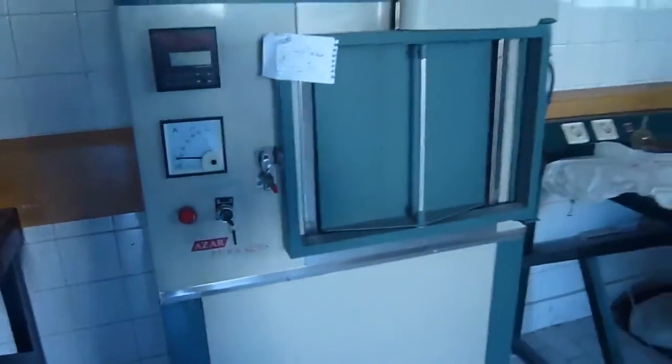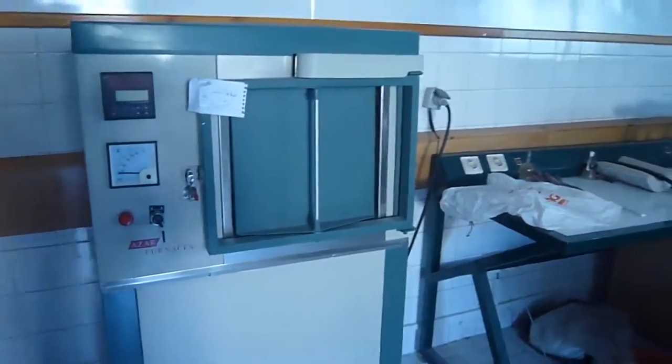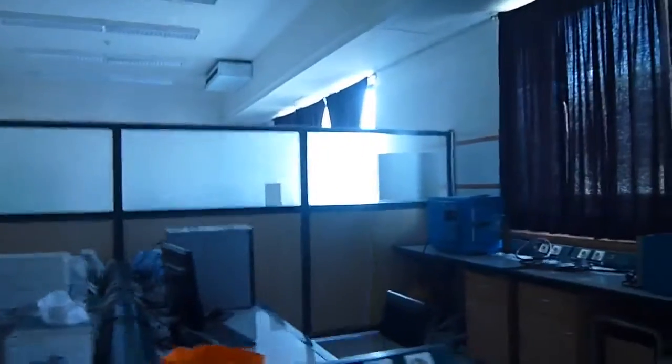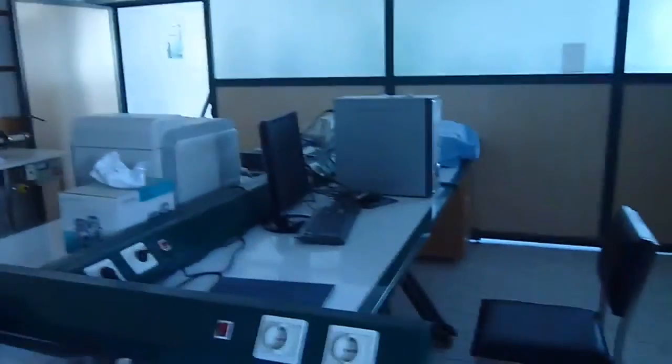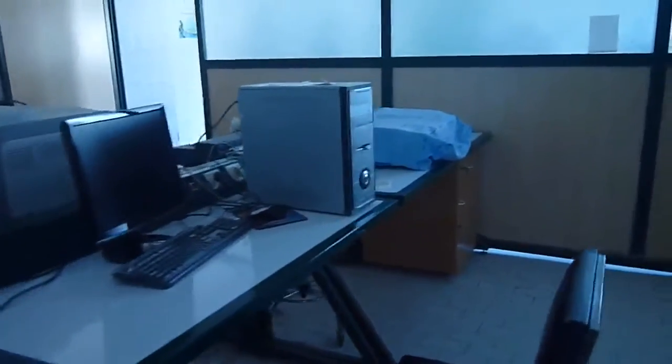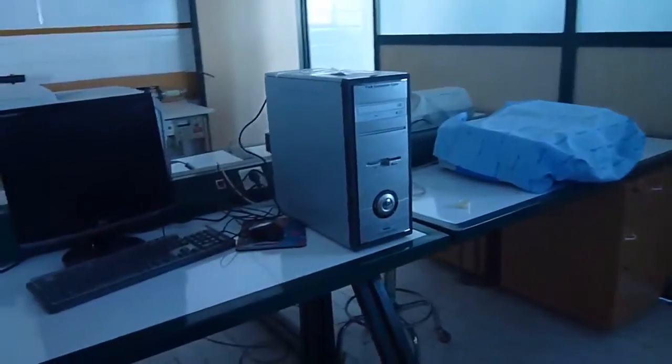Copper, silver, and brass can be cooled slowly in air or quickly by quenching in water, unlike ferrous metals such as steel, which must be cooled slowly to anneal. In this fashion, the metal is softened and prepared for further work such as shaping, stamping, or forming.